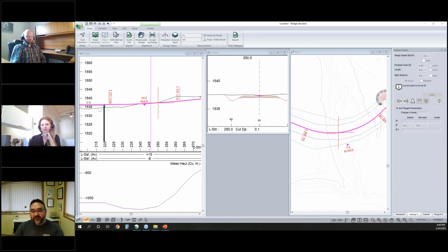But if you're up in that 2 to 3 meter depth, you're going to have a hard time. You're going to have a hard time excavating and replacing, because if you don't bring your fill up above the ground around, you're going to have all sorts of troubles, and you've probably just increased the overall quantity of structural fill you require.